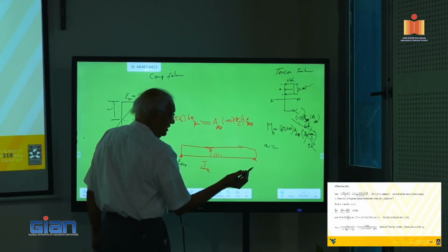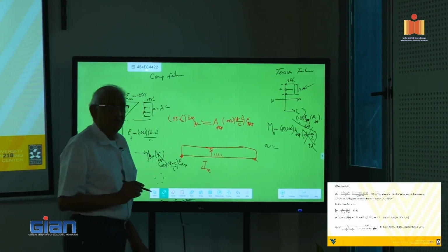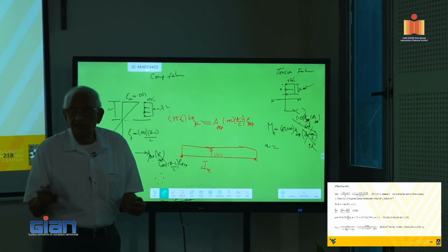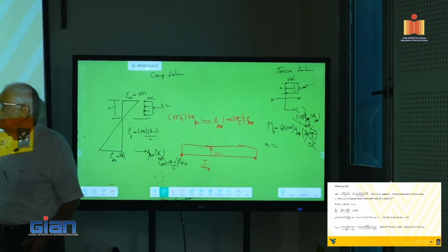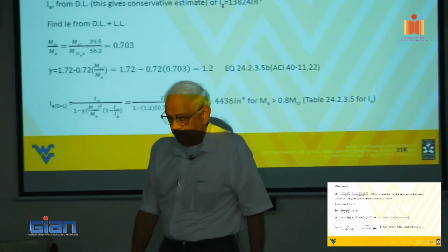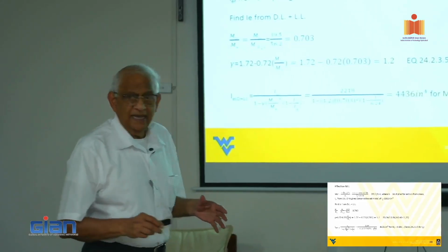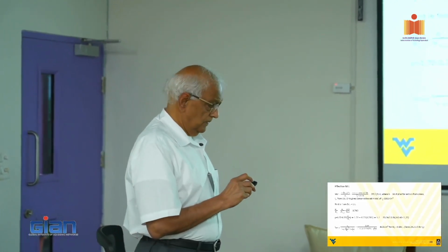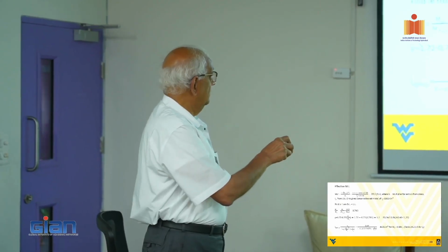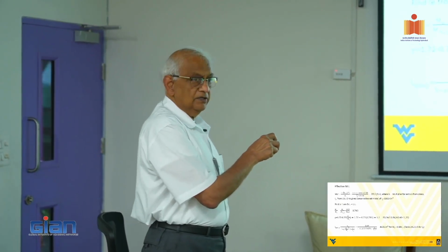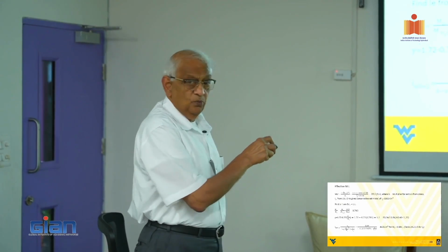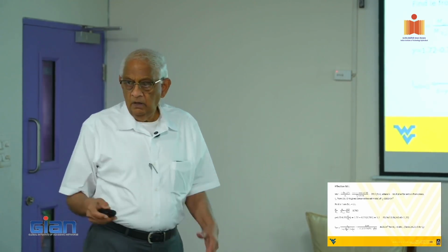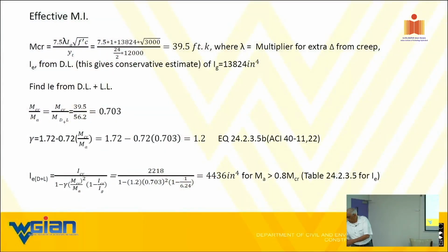as we discussed this morning before the break. How much did it crack? How much do you think it is cracking? That is established empirically based on lab testing and what have you. This equation is the critical equation, and that is tied with M crack, which is the section property, while M sub A is the applied load based property.